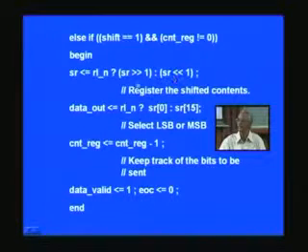And either this thing is assigned to SR or this one is assigned to SR. Here is the right shifted content, here it is the left shifted content. So that's what goes to SR. SR once again is 16 bits, therefore this result is also 16 bits, each of these results. Whereas this is only 1 bit, and the comment says the appropriate thing here, register the shifted contents.